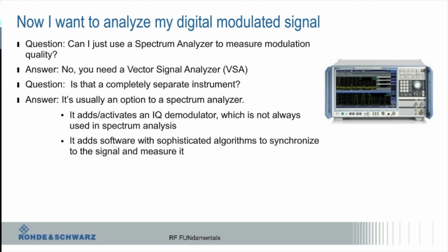So in the simplest case, when we talk about VSA, vector signal analyzer, it's letting you define a generic waveform. You can say I have a QPSK signal, and it has this type of mapping, et cetera, and I'll show you that in a sec. And then it'll let you decode it. And you can generate a similar thing on your SIGGEN or device or whatever, and it'll allow you to measure metrics from that device.